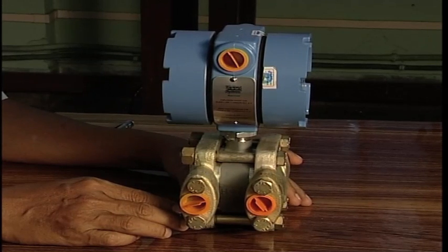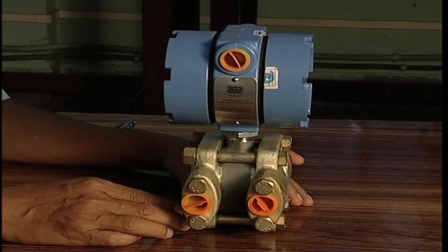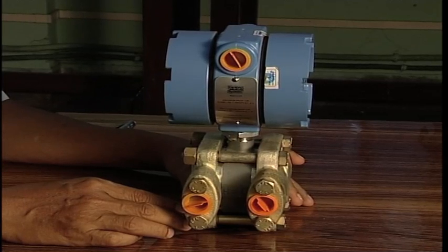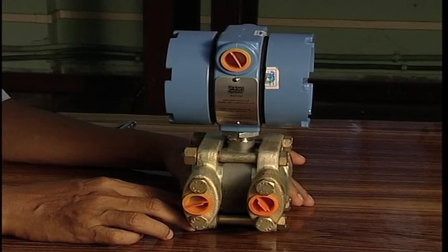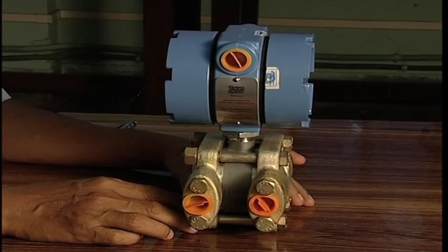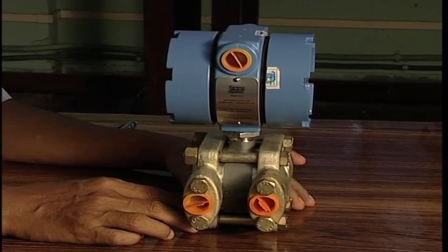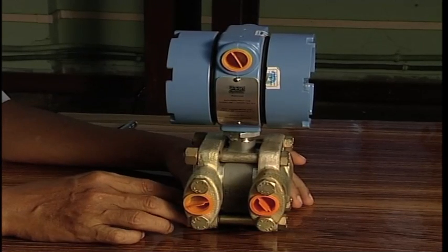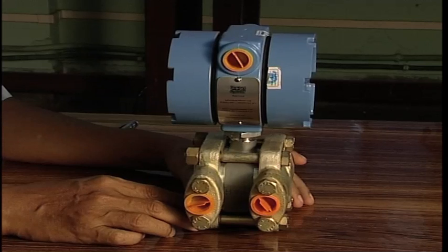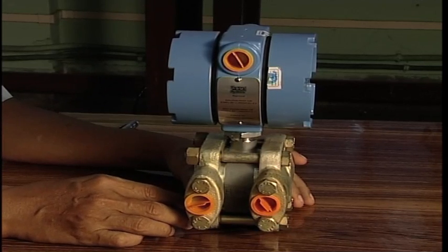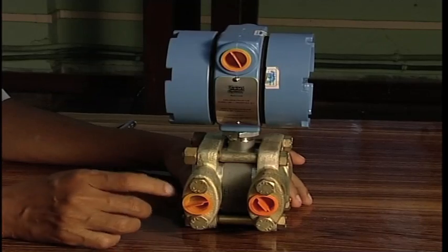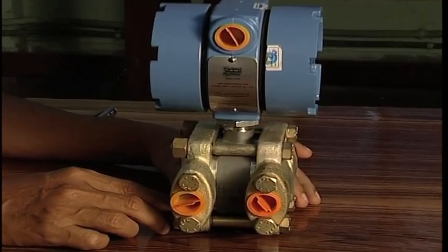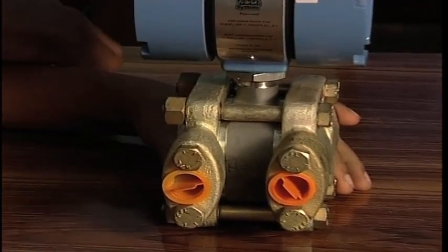We have seen in the class that we have shown a manometer sort of thing, by which I am measuring the pressure. But unfortunately, in an actual process, I need some instrument or equipment which will give a signal that will be transmitted to the control room. For that reason, we need some electrical output. So, in this differential pressure transmitter, there are two pressure taps, one upstream and another downstream.